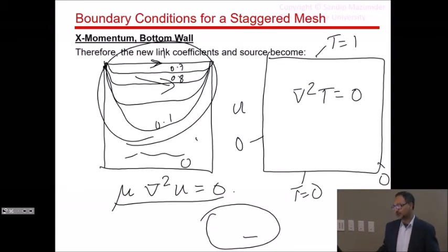So if it's working first iteration, let's say you've checked your U momentum, you've checked your V momentum, both are working, okay? And let's say somehow you've also figured out your pressure correction equation is working correctly. But then you find second iteration, first iteration everything works, second iteration, boom, residual goes to 10 to the power 34. What may have gone wrong?